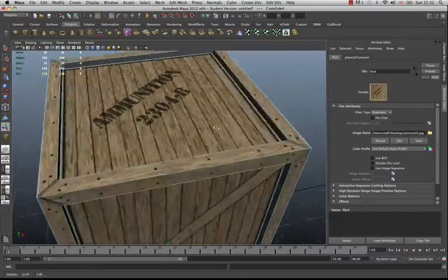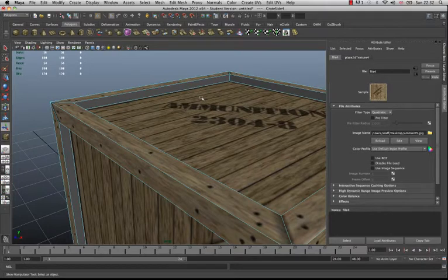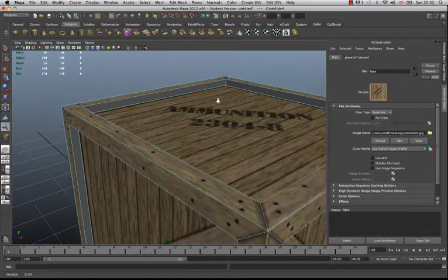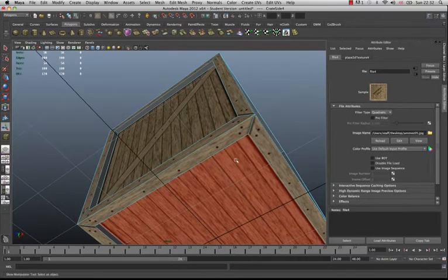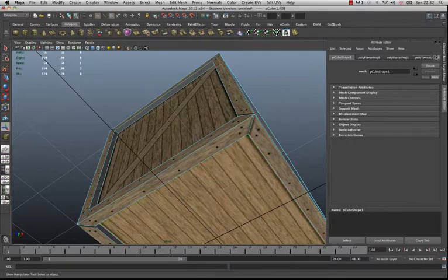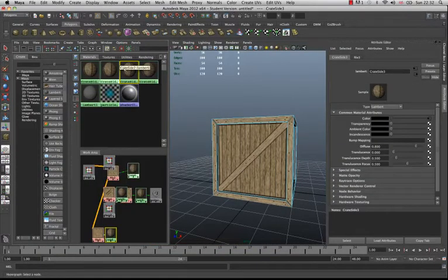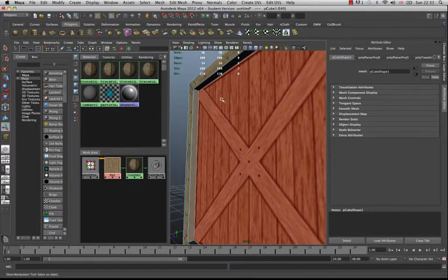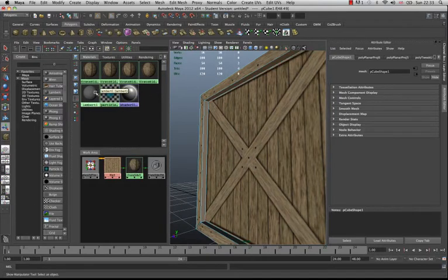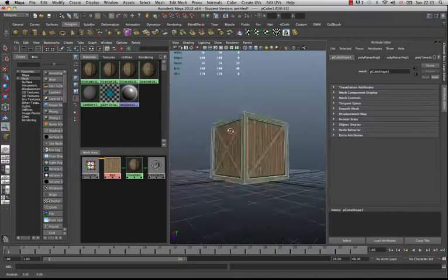Now, we have been left with a load of blank edges, as you can see. Now these, I'm going to create one shader, which will be this shader on the bottom. In fact, we'll just use this shader on the bottom. So this was shader, we have a look at this one. This one is shader 4, side 3. Let's just focus on that one. And what we're going to do is select all of these faces. We're going to do this by simply going right mouse click over Lambert 1 and select objects with the initial shading group. There you go. It selected them all for us.